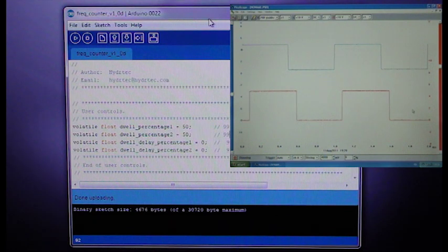First thing I'd like you to note is, whereas the input pulse starts here, incidentally I've got it set to trigger on the rising edge of channel A, which is this, at 4000 millivolts, because there's a slight amount of variance in this range, and to guarantee no jitter whatsoever on the display I've set it to that value.